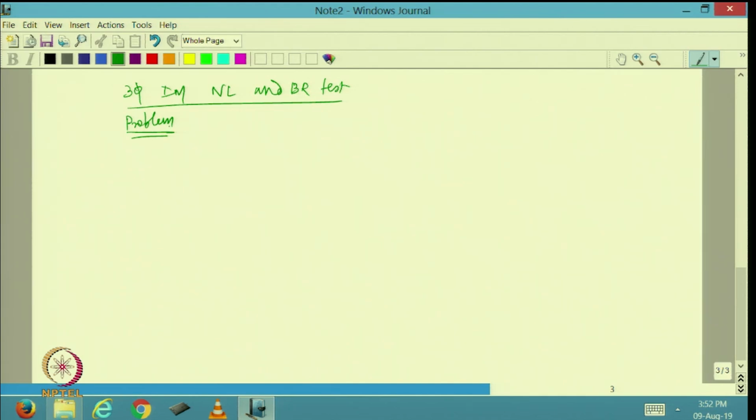I am going to have basically for open circuit test for a 3-phase induction motor, the readings are somewhat like this. It is 2200 volts, 60 hertz, 4.5 ampere, and I am essentially getting a wattage reading of 1600 watts.